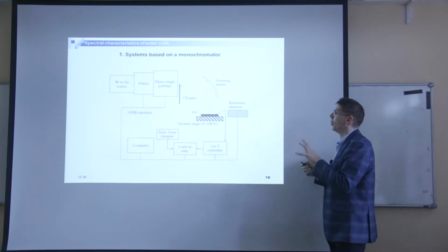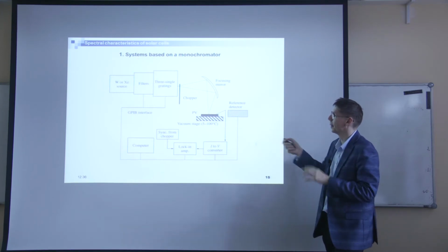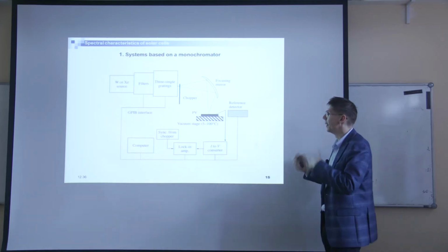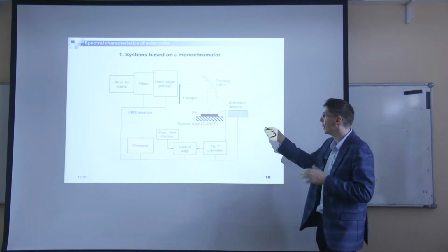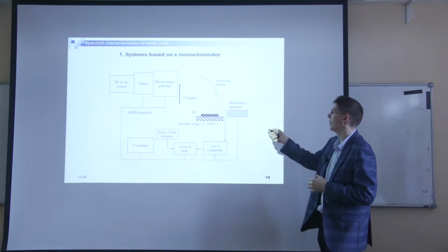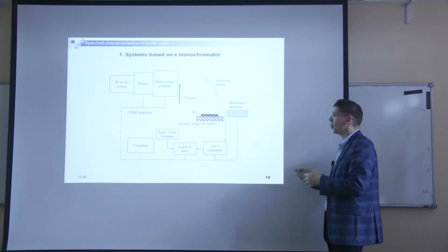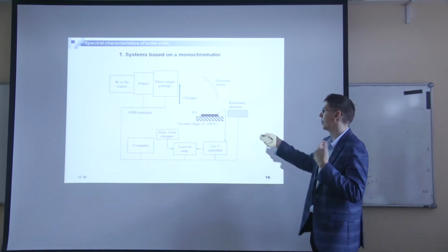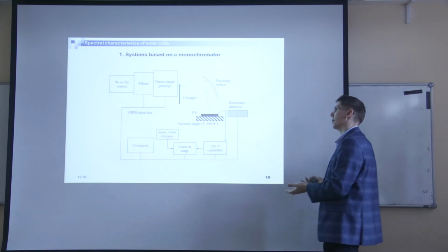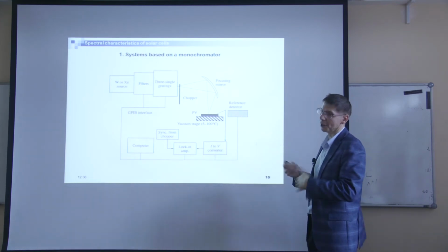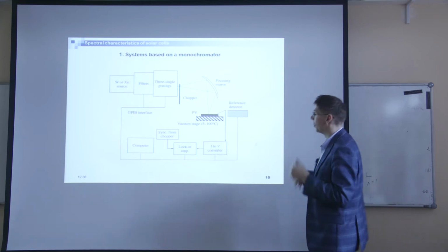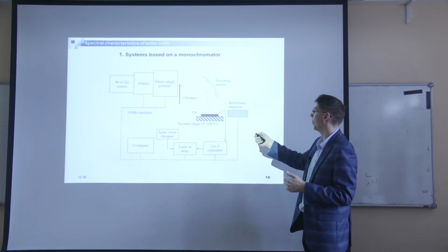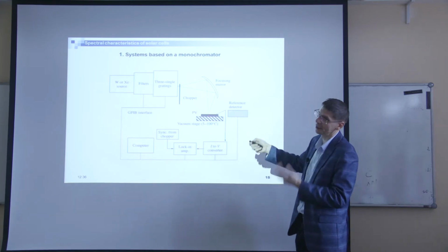normal procedure is that first of all you measure the reference, so I mean, just measure the intensity, the spectrum intensity at each wavelength. So you measure with the reference detector, then you measure the spectrum with a test solar cell. So I can make a few measurements of different solar cells, and then again check if the spectrum is the same. There is another way to measure at each wavelength. So to change detector: solar cell, reference cell, solar cell, detector.